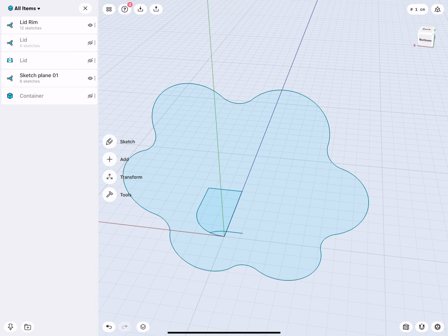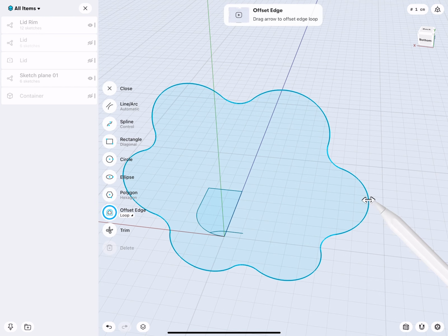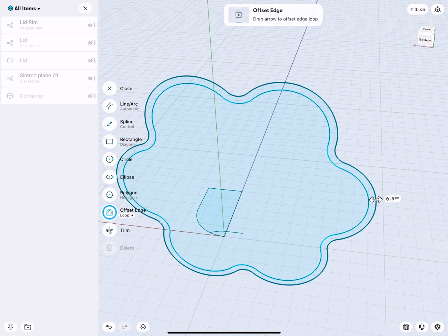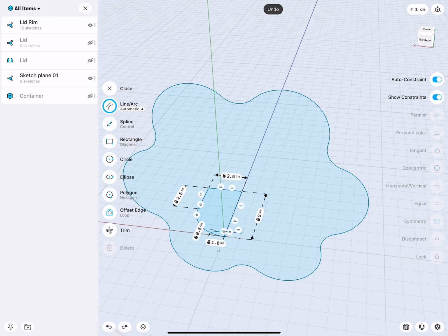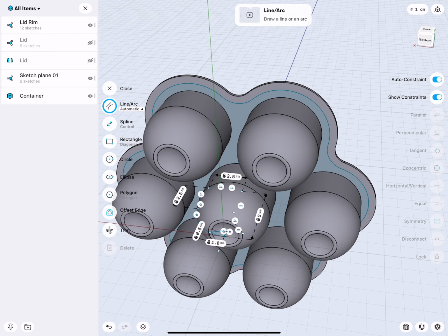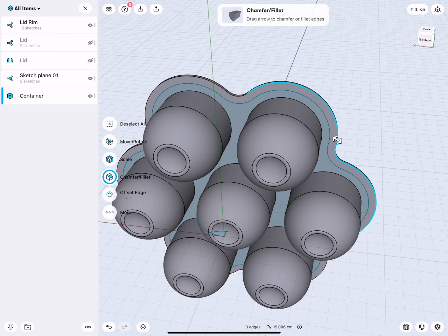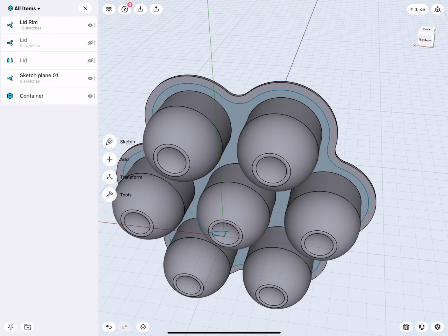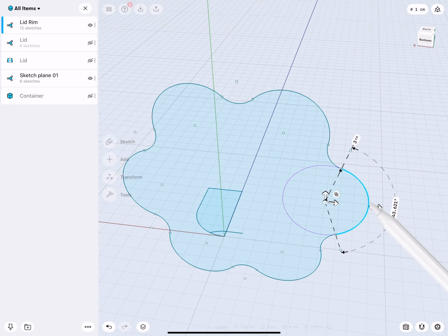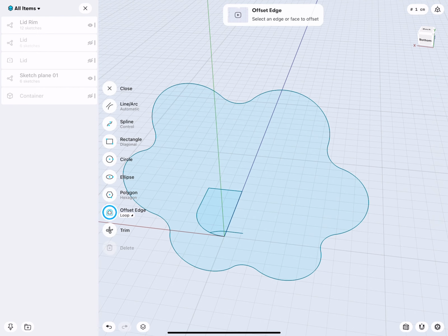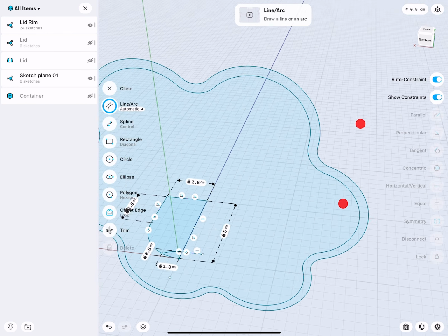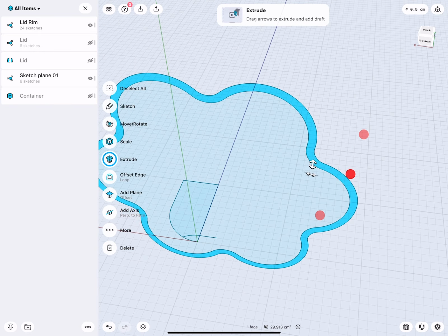Go back to Sketch and Offset. Select this one more time. We could offset this back by 0.5 if we want to, or I could also, just to show you the options, select all these edges, select the sketch, and then use the project command. But I have to select all the edges, which is why the offset with loop here simply works. Very good and easy.